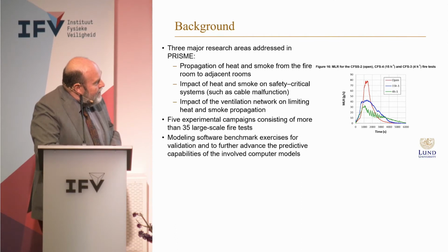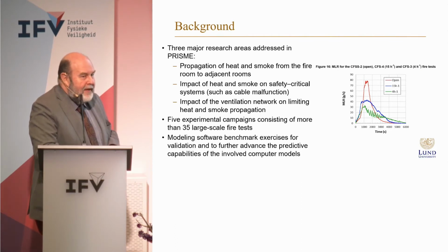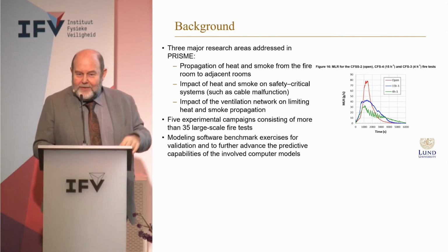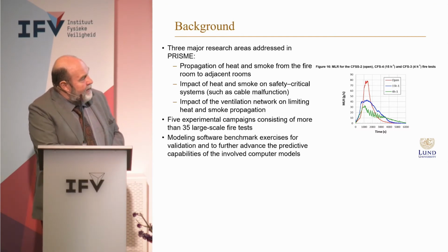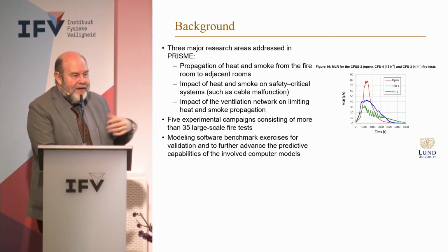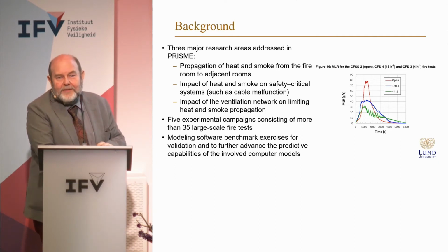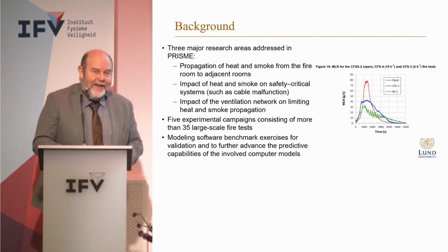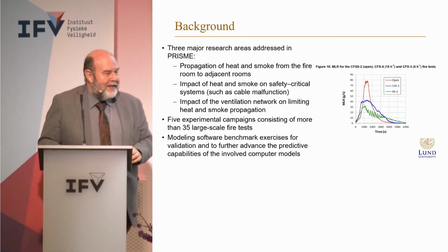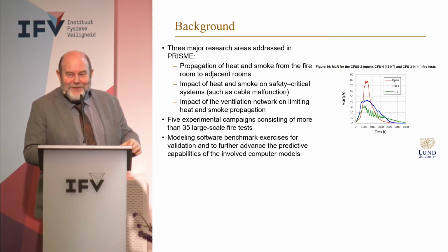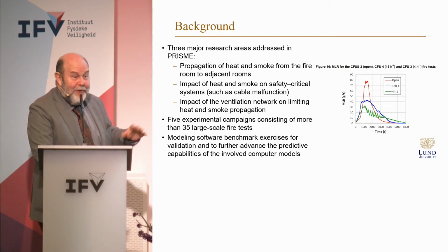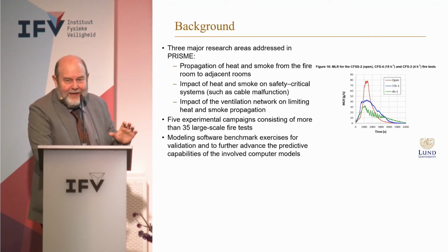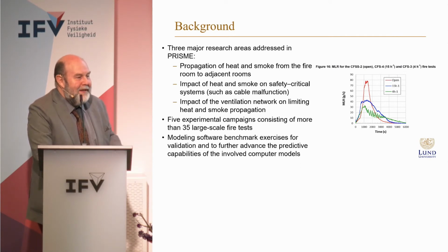What's happening if we go down, you see this peaks up and down. And that doesn't mean that the computer didn't like the measurements anymore and started to measure mass loss rates up and down. No, it's really that the mass loss rate is going up and down because you get a kind of breathing, a back and forward of the mass loss rate. And if I push it towards, I've seen now on the monitors that it's about 40-50% fire brigade here, because I could see that in some of the results. What does that mean? These are fires you don't like because you don't know what's happening. They are under-ventilated. And if you open, you all probably know much better than me what can happen.